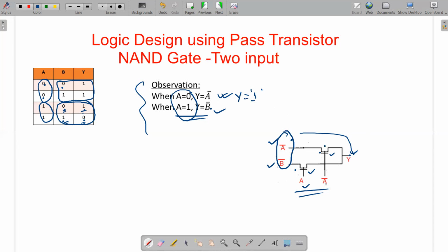You can take A as a control signal, and if you want you can also take B as a control signal, and you can establish one relation between A and Y. That is also true, you can do that. But remember that this structure will also follow the same behavior, whether this transistor is on or that transistor is on. If the input is a logic 1, the output you will get is VOH minus 1 VT. That means one threshold voltage drop will take place.